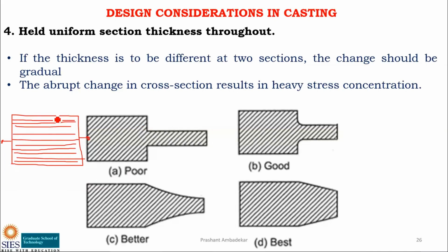But instead if I cut here and cut here the material, now these stress flow lines which were going straight, now they will go like this. The bottom stress flow line will go like this. Then this will go like this. And see what is happening here. At some place there will be congestion. You can see there will be congestion. Where is the congestion? The congestion is here.